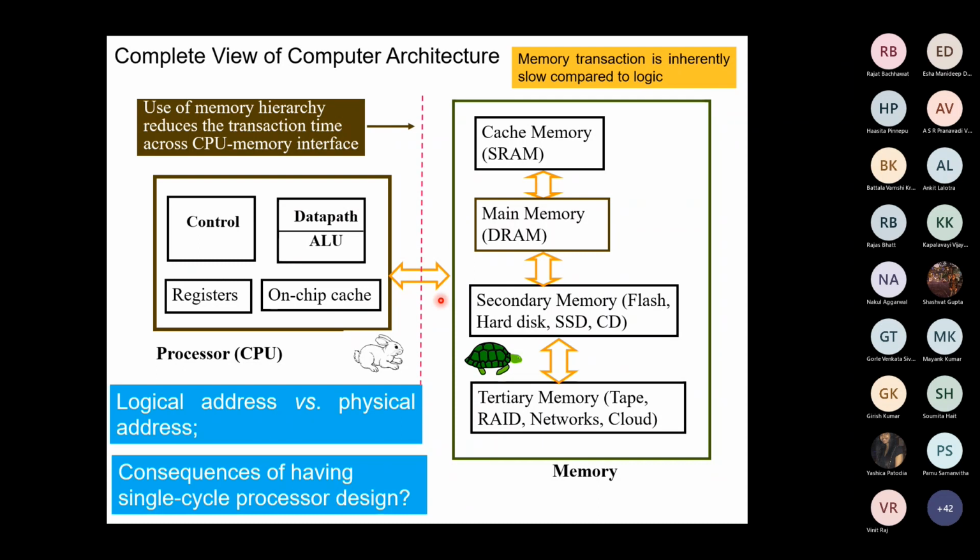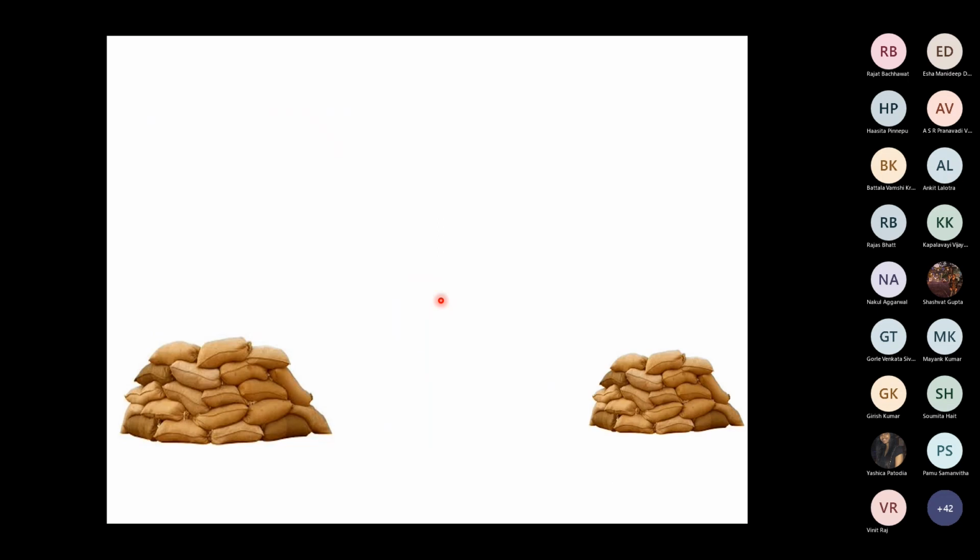So I'm talking about single cycle processor design. Then what should be my clock cycle time? The maximum possible time for an instruction to execute. Okay, so this is almost infeasible, isn't so? If you are lucky and you find the instruction or data in the cache, fine, you just find them in one shot. But you have to prepare yourself for the worst case as well, and therefore this is infeasible because you have to extend the clock cycle time very long. So what are the other possible solutions?